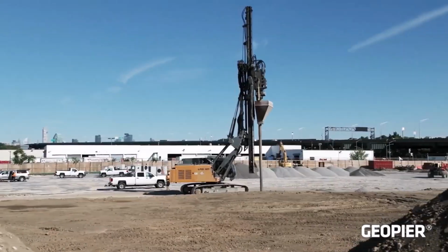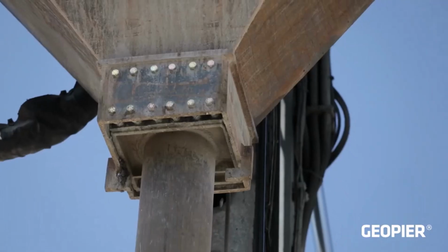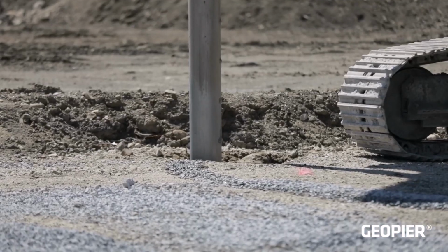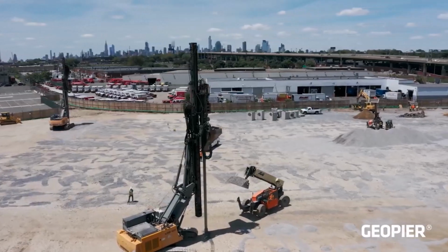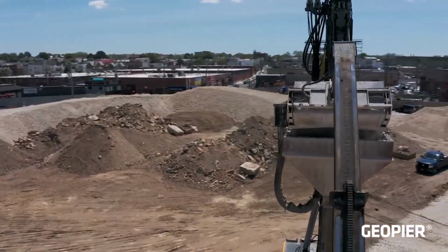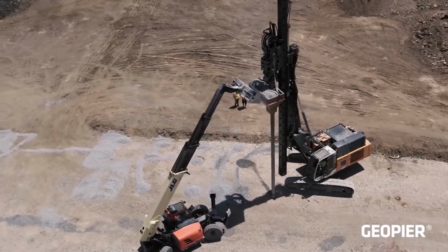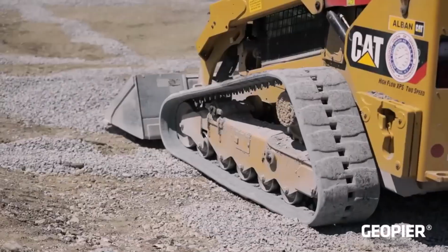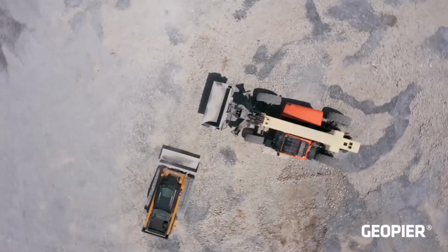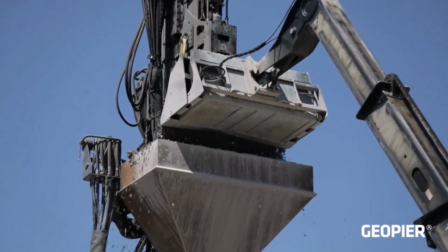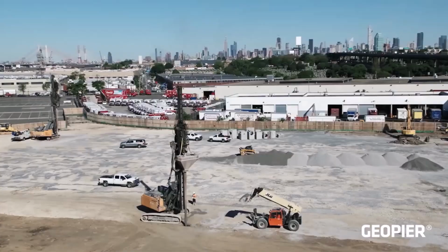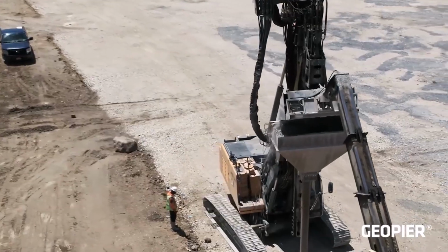The Geopier Impact rammed aggregate pier option was chosen as it allowed the urban fills and the coal ash to remain in place at much lower cost than providing a deep pile foundation option. This ground improvement system was chosen because it was able to support high slab loads up to 600 PSF and much higher than normal column loads that will eventually support the building and the above ground parking structure.